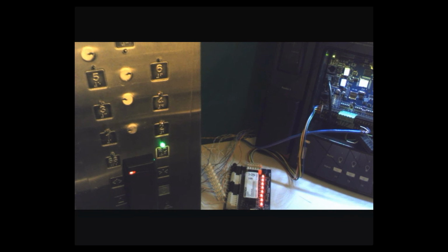Once the save button is clicked, meaning I told Entrapass we have this relay module and we will be using it for elevator control, two things happen. First, the relay, since it was already wired properly, is linked and is activated, defined. Automatically, all the relays came on. You see all the LEDs, they are all up and running. Why is that? Because in our system, once you have a relay module defined for elevator control, the relay is automatically activated, meaning you need to do your wiring accordingly, knowing all the relays will be up, meaning the floors are disabled.